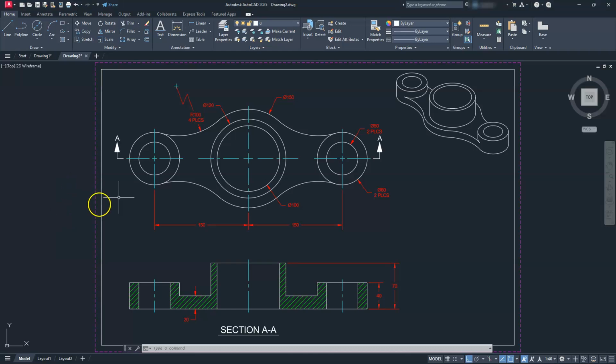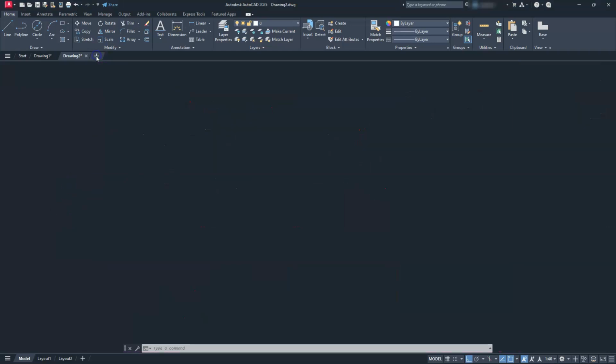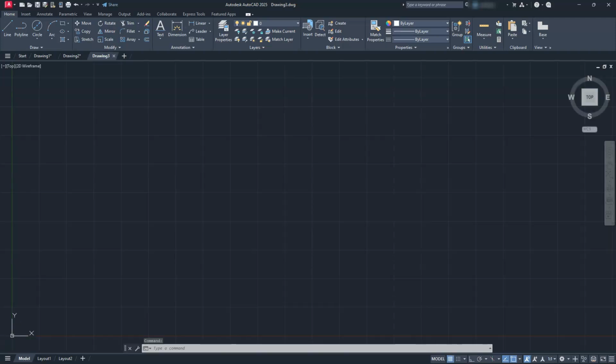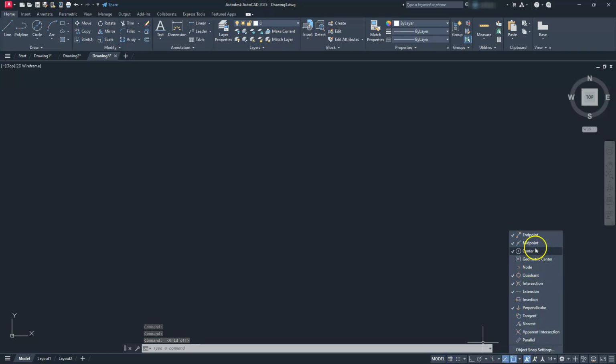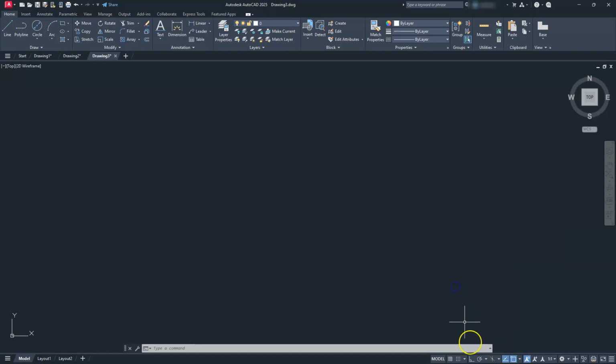All right, so continuing from here, let's go ahead and open a new drawing. And then we're going to set up all the normal stuff that we do. We're going to turn the grid off, and we're going to take a look at our running O-snaps. So these are going to be the ones that I'm going to use. And I also like to turn my ortho on. Okay. So the next thing we need to do is switch over to 3D AutoCAD. We're going to do that by selecting the settings icon here and then switching to the 3D modeling.